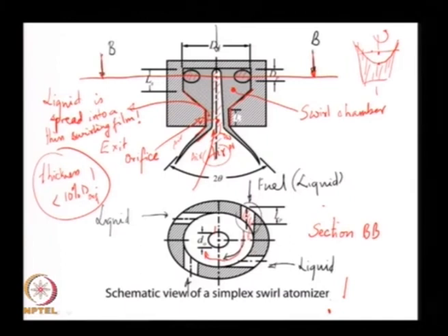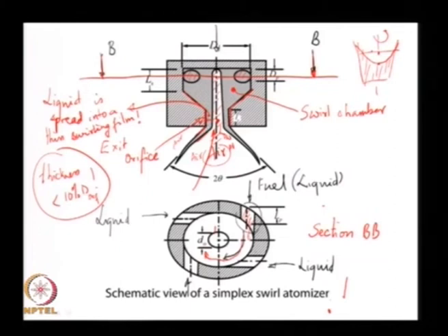Both of these put together allow us independent control of the mass flow rate and the drop size over a fairly large operating region, and that is I think the main reason why this particular nozzle design is widely used. In fact, the real reason it has found wide commercial applicability is because I am not constrained by this orifice size, this D orifice, which can be a fairly large value.